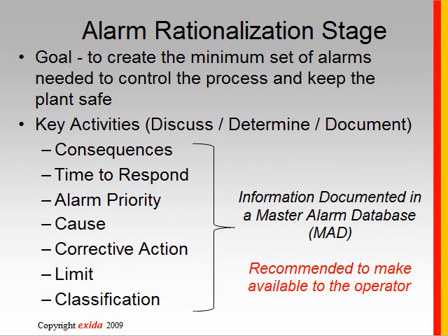Another recommendation of the standard is that all this information should be defined and recorded in a master alarm database. This can be a tool, this can be the control system configuration, it can be an Excel spreadsheet, it can be an Access database, but the idea is to have a master record of what all the alarm settings are supposed to be.